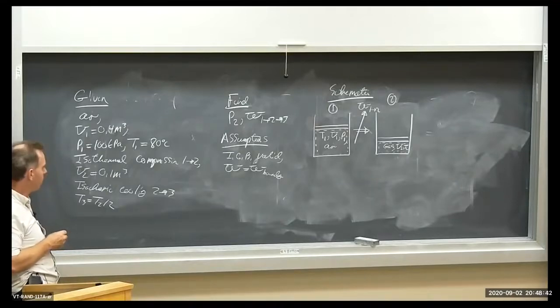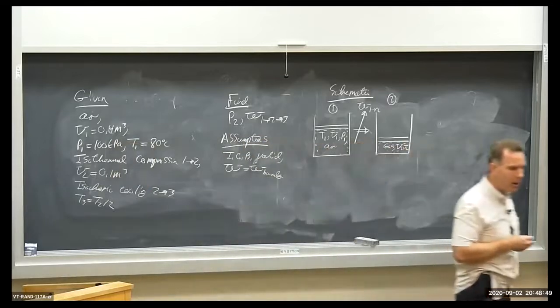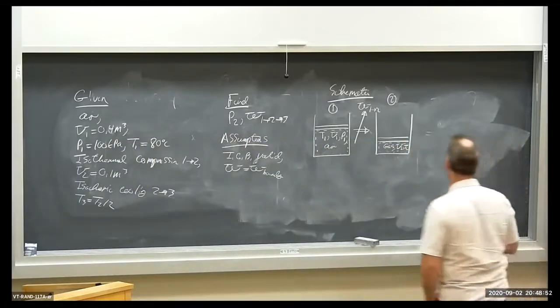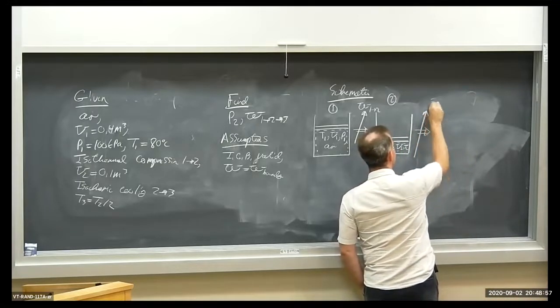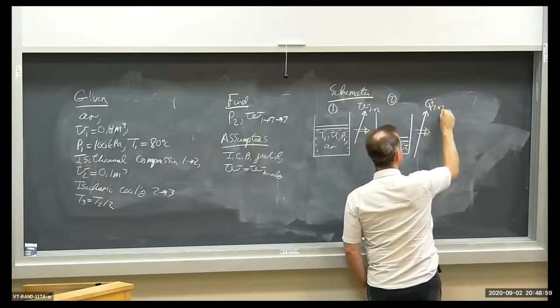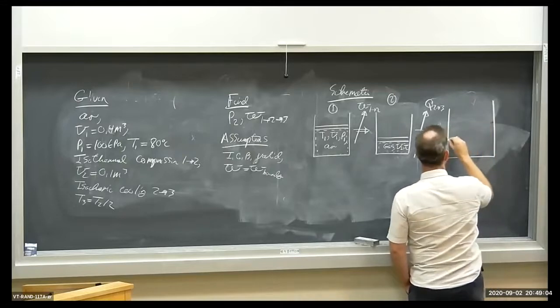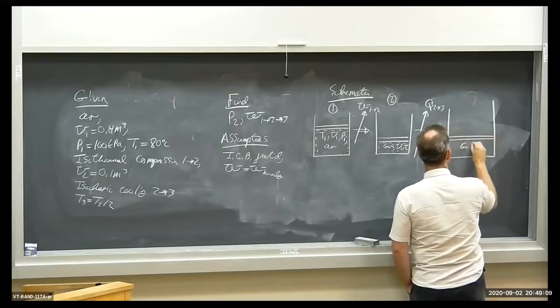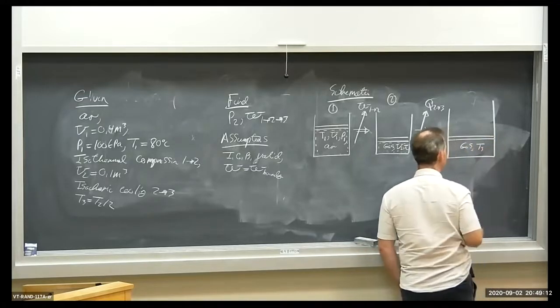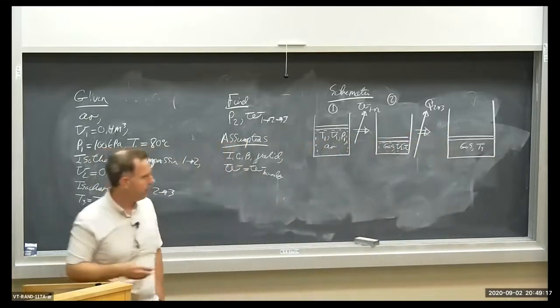We'll have to see. So once we squeeze the gas down for an isothermal compression process, then we have an isochoric cooling process. We transfer heat out of the gas, we cool it down, and we do it isochorically. What does isochoric mean? Constant volume. So then heat is being transferred out of the system, let's say. And it's an isochoric process, so the piston doesn't move. Here's our gas, and we end up with a final temperature T3, final volume V3, et cetera.